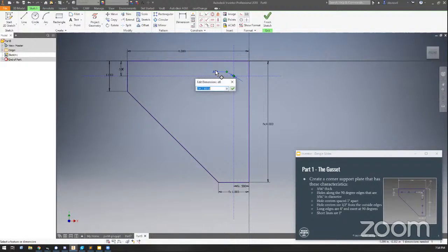I mistyped. Okay, so now I have this circle that's here. Now, if I move this, you can see that it's still green. I tried to get it on the point, but I must have missed. So anyway, it's got one of the constraints because it's stuck on this one, but it's not stuck on the other one. So I'm going to take this, grab the center, and also constrain it to that line. Okay, so now we've locked in. So now I've got our first